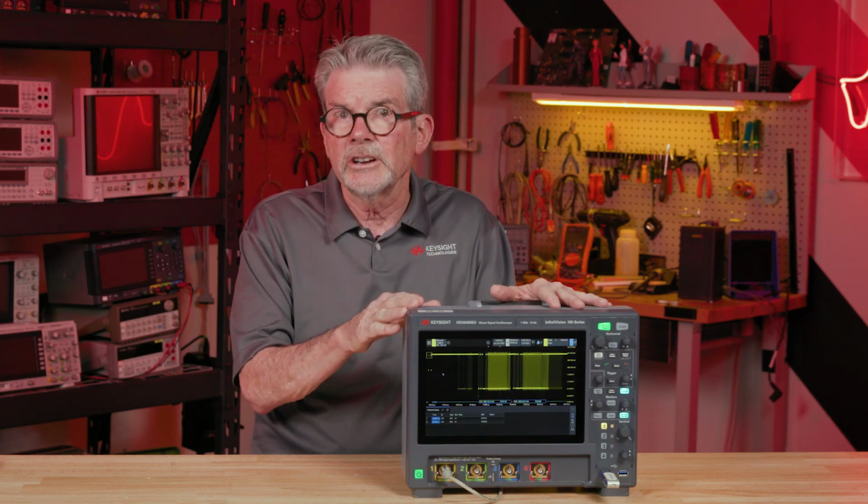Although this demo focused on some of the benefits of using this scope for embedded designs in consumer electronics and automotive applications, this scope can be used for a broad range of industry applications where high resolution, low noise, and support for common serial buses are important. The HD3 oscilloscope comes in bandwidth models ranging from 200 megahertz up to 1 gigahertz. This scope samples at a maximum rate of 3.2 gigasamples per second across all channels simultaneously, along with 100 megapoints of acquisition memory for each of the 4 channels.